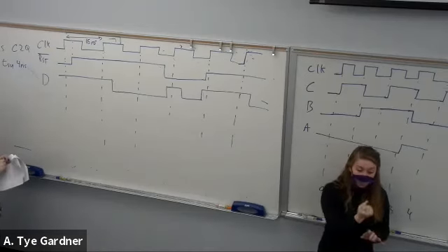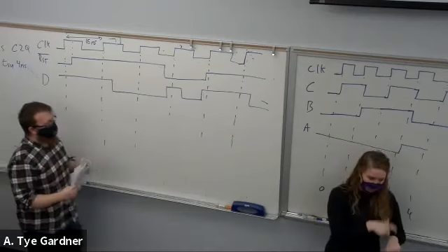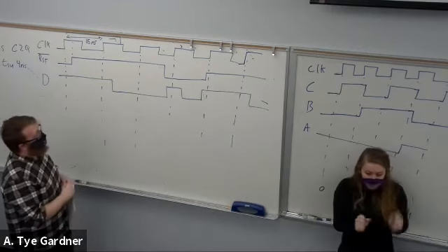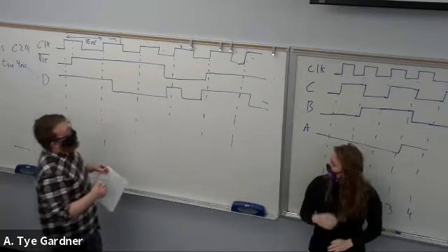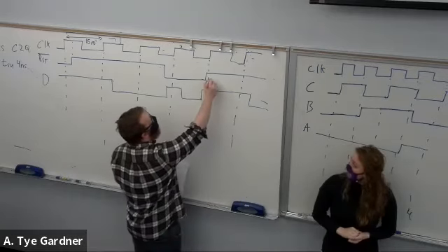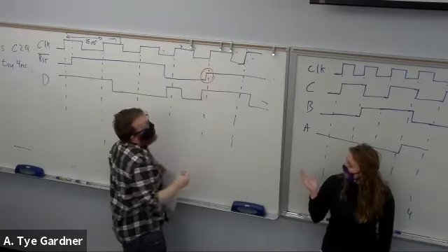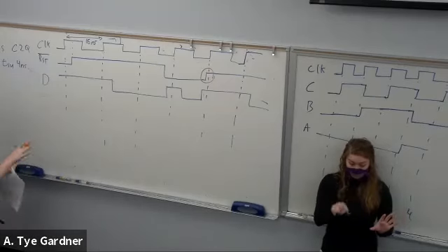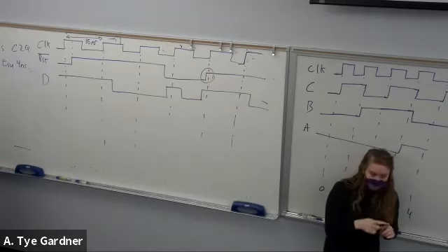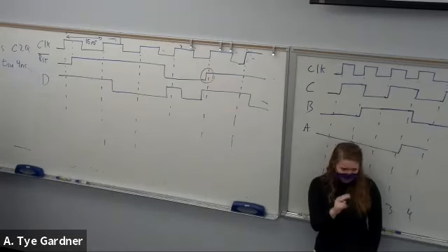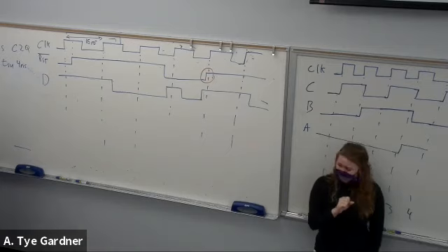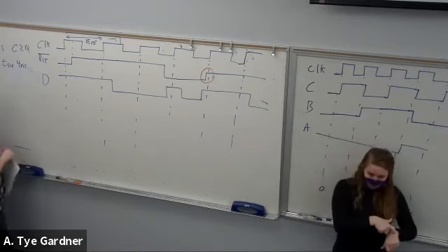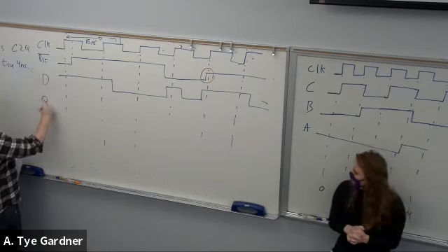Well, let's take a peek and identify some spots that might be problematic. Here is the most apparent issue. That doesn't look like, even in my terrible drawing, 4 nanoseconds. I don't meet setup time there. All right, well, let's do Q first.